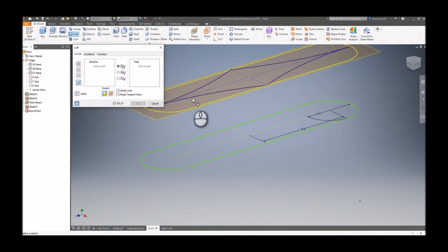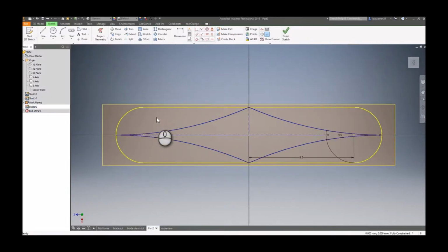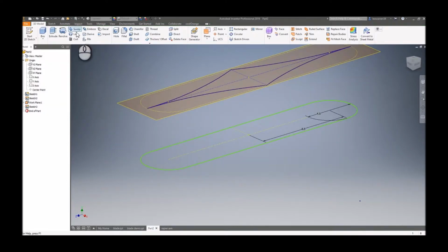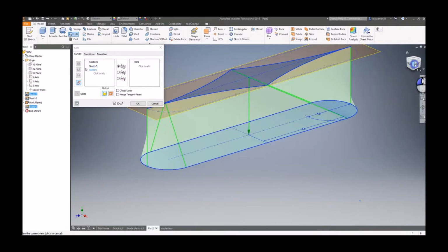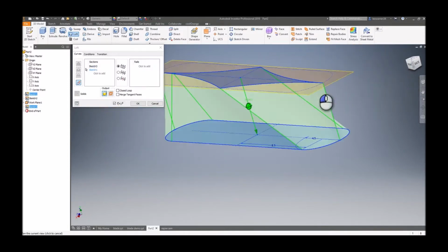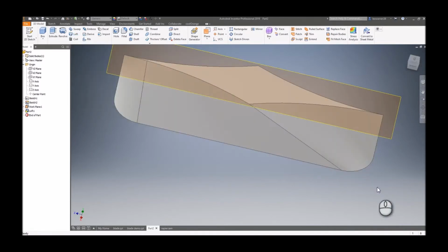But you'll see the first problem we're going to have, if I just select that, is that we actually have to set the projection to a construction line. Otherwise that's going to try and join the loft, which should be the first source of your problem. Now we have just the profile. The biggest problem you'll notice is that when you do that, you don't always get nice swept, nicely lofted edges. See, it kind of wants to try and go across itself.